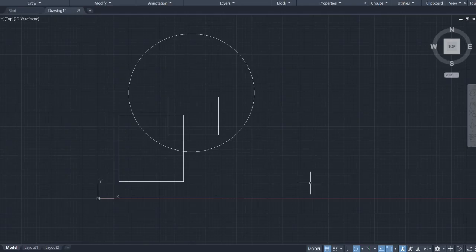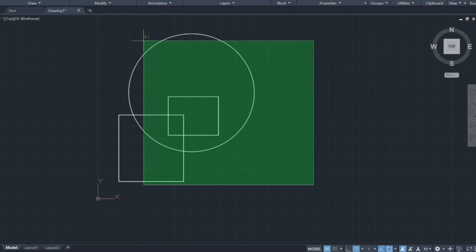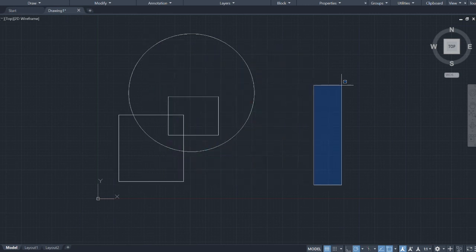To make our highlighting green, we click, then we move our mouse to the left. Okay? So, if you move your mouse to the left from where you clicked, you will see a green highlight on the rectangle. But if you are going to move to the right side of where you have clicked, then there you can see a blue highlight. That's it. That's easy.